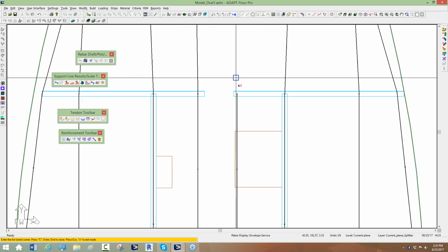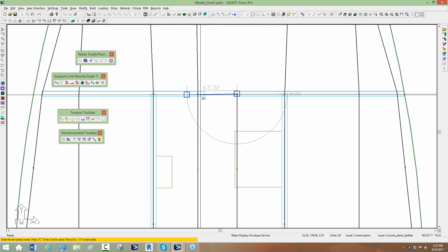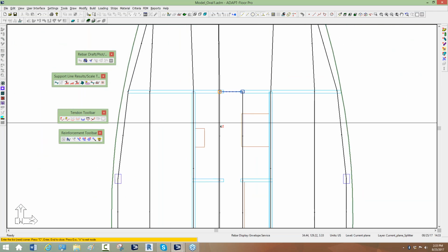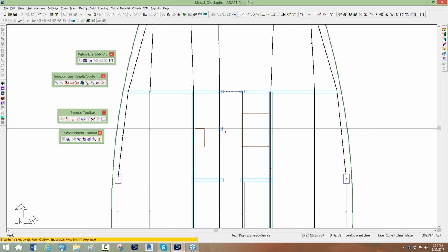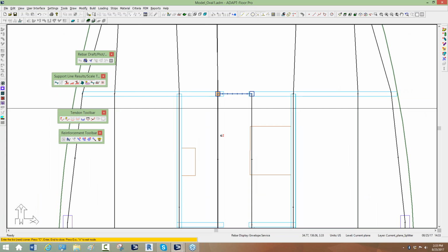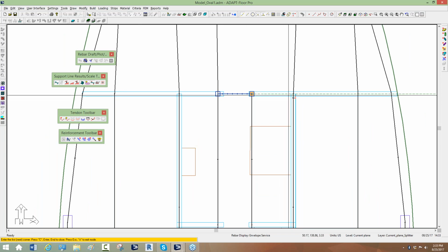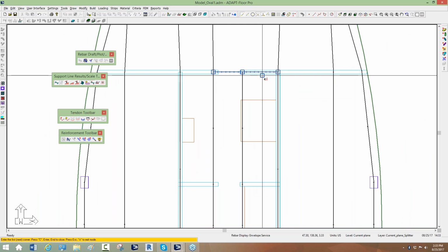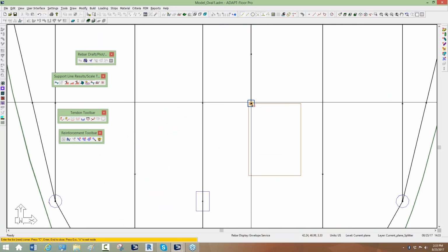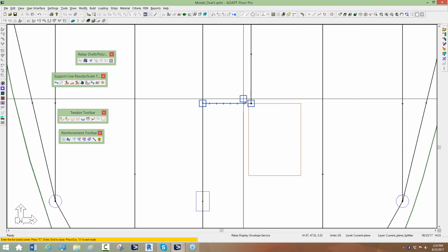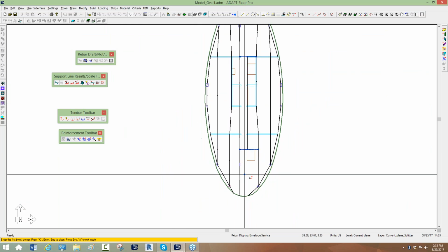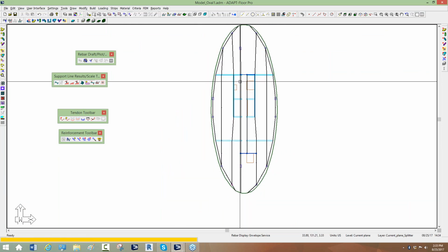So I'll take this, I'll start it at this point, and I'll go to the left side. I'll terminate it at a slab edge or at a continuous support line, whichever comes first. That's the basic rule of thumb. So we'll stop it at this support line, and I'll do the same thing there. There's my virtual boundary, which stops the tributary, and we'll do the same thing on the opposite side here. So that's the first location of a splitter.